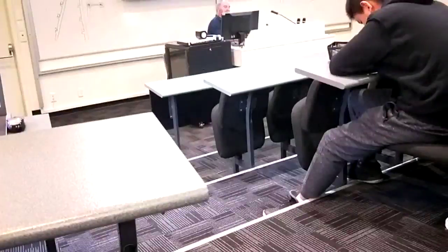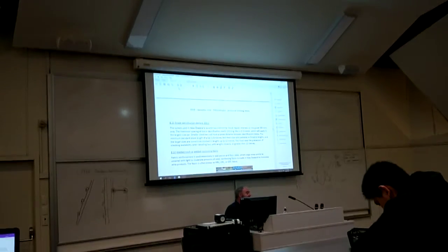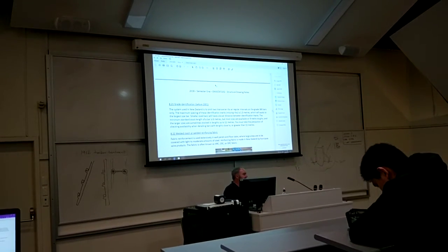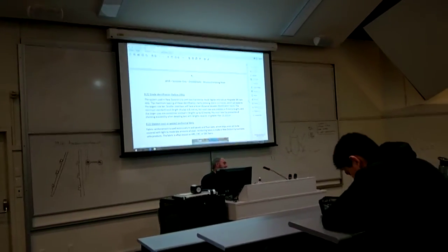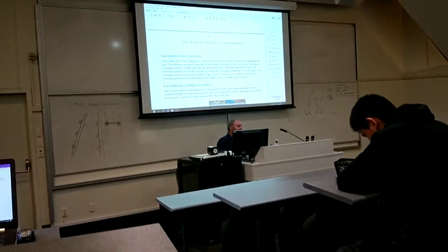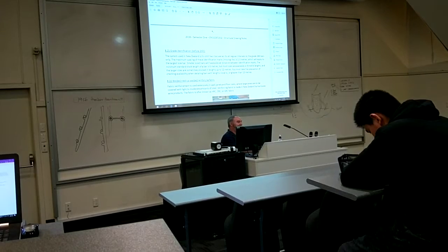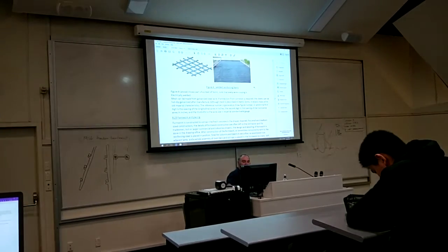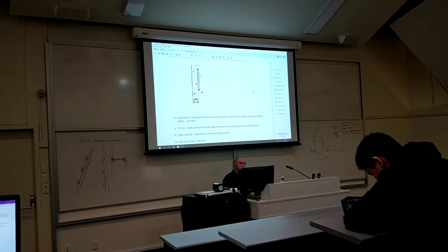I just wanted to point out in the notes that in the real world we do ring up the suppliers and work out what's available. Also, there may not be any, say, 16 bars, they might be out of them. So you've either got to wait 6 months and tell the client, sorry, you're going to wait 6 months, or you go, actually, no, I'll go to 20. Well, we'll pay a bit more. So you have to tell the client it's going to cost more, but you get the building tomorrow. So it's like anything, like bricks or steel as well. So when you come to do steel next week, you'll see there's a chart exactly the same.